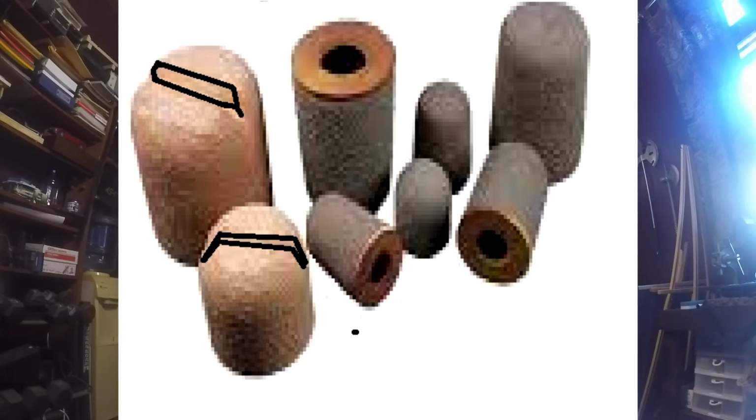But after you make that, you've got to cut a wedge or a notch in the top. What that does is allow the permeability in the sand to give you some atmospheric pressure on the top of that, so that there's no vacuum being formed as it's trying to feed whatever it's touching. And if you formed a vacuum in there, it might be a little bit hard for that metal to be drawn into the mold cavity, as the mold cavity is solidifying and it needs to be fed.